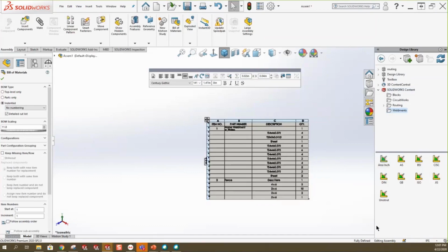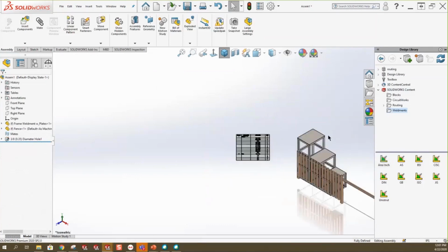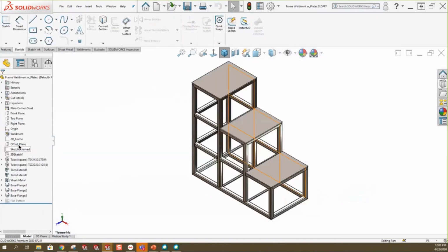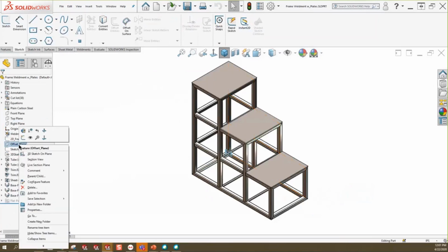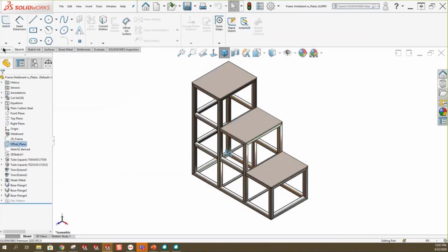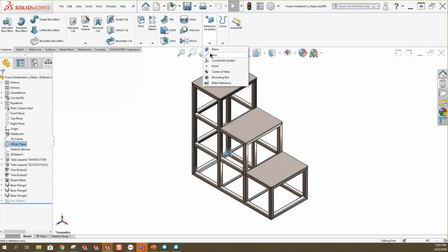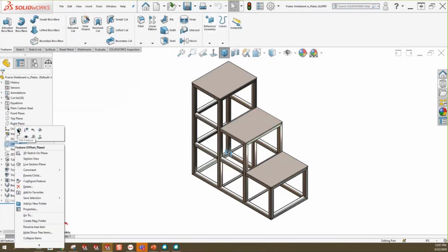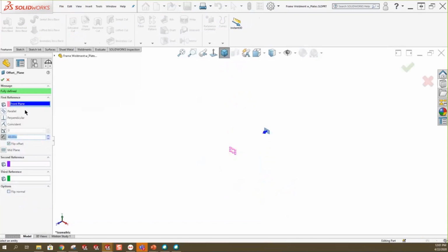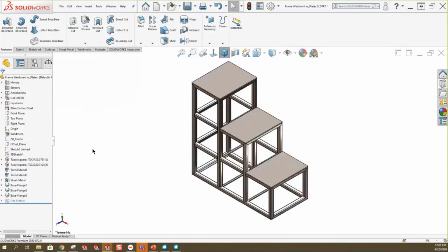Let's see. I use a different technique offsetting planes. Can you show the offset plane command? Interestingly enough, I'm going to go back here, and you may laugh about this. Actually, all I did to create my offset plane is I went to features, I went to reference geometry, plane, I defined the distance off my front plane, and I named it. So there might be a cheat compared to that question on how to make that.